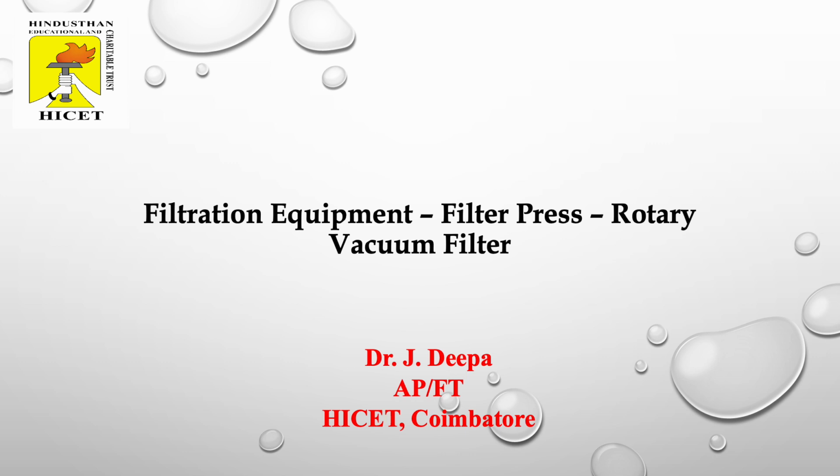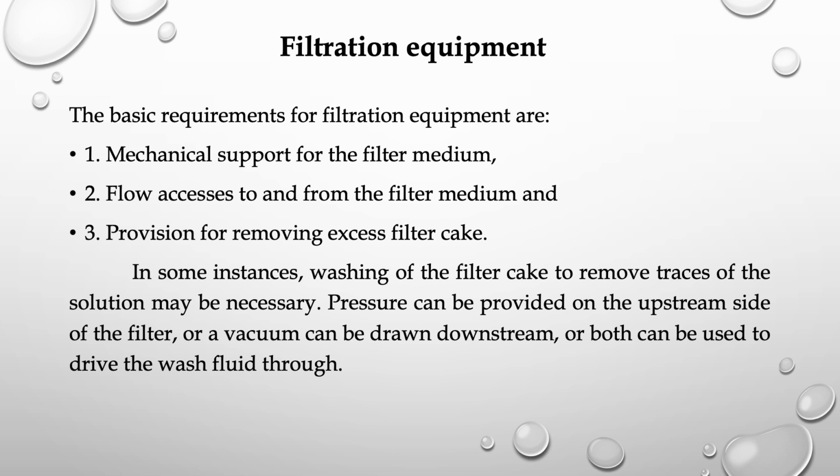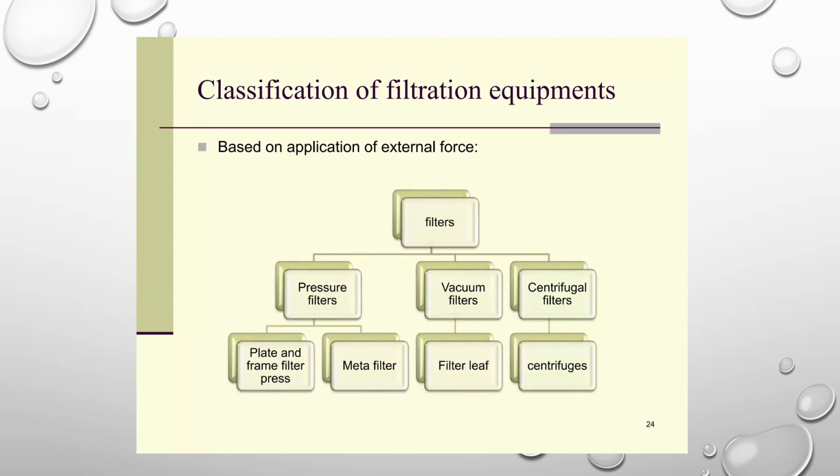In this video, we are going to see about the filtration equipment, mainly the filter press and the rotary vacuum filter. If we see the basic requirements of any filtration equipment, mechanical support for the filter medium is a must, it should have flow access to and fro from the filter medium, and it should also have provision for removing the excess filter cake.